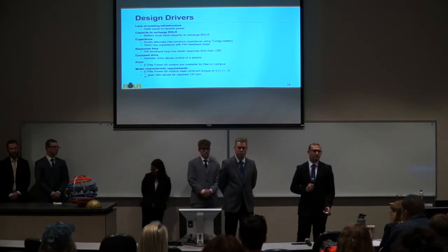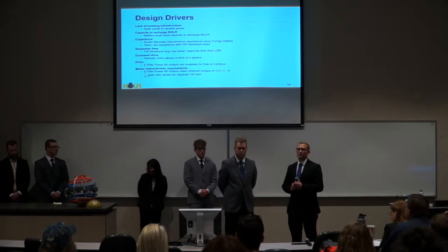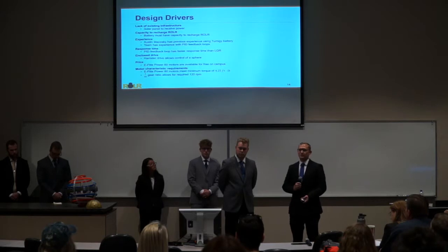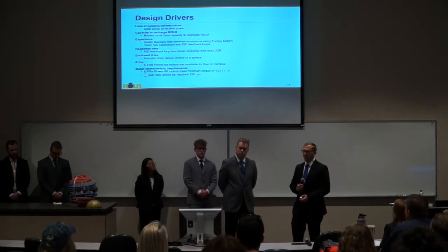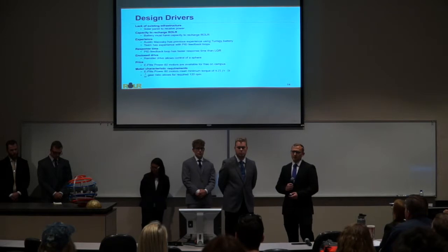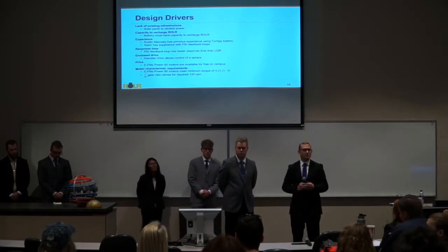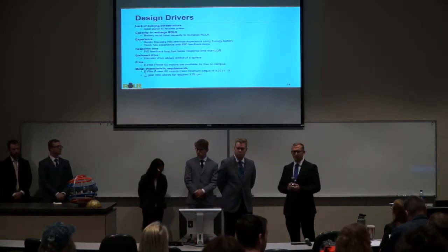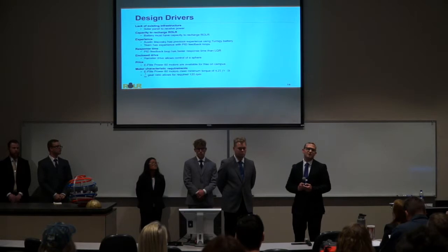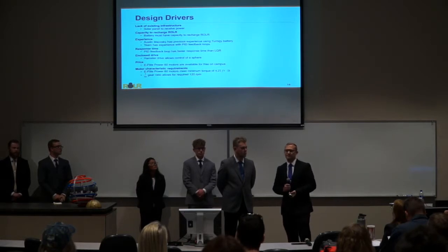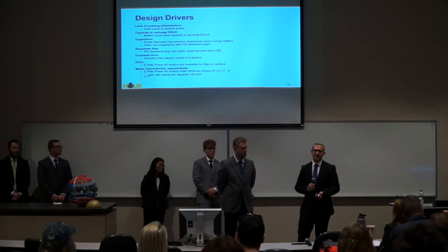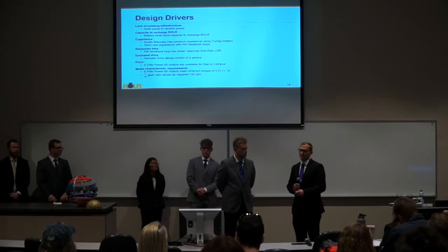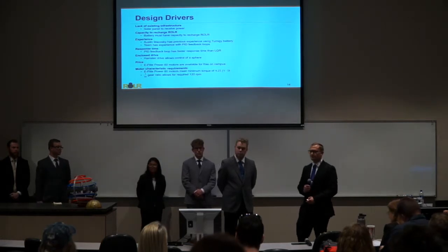Also with feedback loops, we found that the PID feedback loop is much quicker than an LQR, so we're going to do this because it's much more time efficient for what we need at this time. Our hamster drive, we're going to be using an enclosed drive system because we have a spherical shell. Also price, we found around campus some E-Flight Power 60 motors, and those motors will also be able to fit our motor requirements, as well as the 1/50th gear ratio that we'll be using.